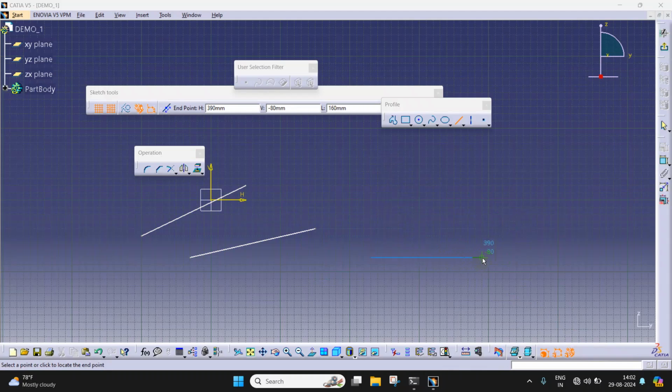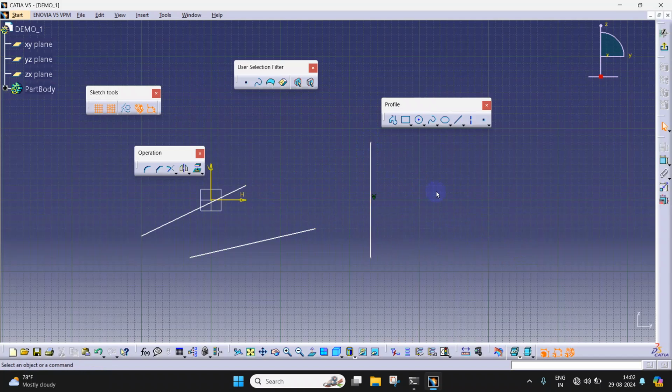so as you can see here, the interface itself helps me to make sure that the line being drawn is either horizontal or vertical. If it is either horizontal or vertical, it appears in blue. Otherwise, it may go white. So in order to make it horizontal or vertical, just be sure that your cursor is exactly at that location so that the line would appear in blue color, and just click the second point to confirm the line.